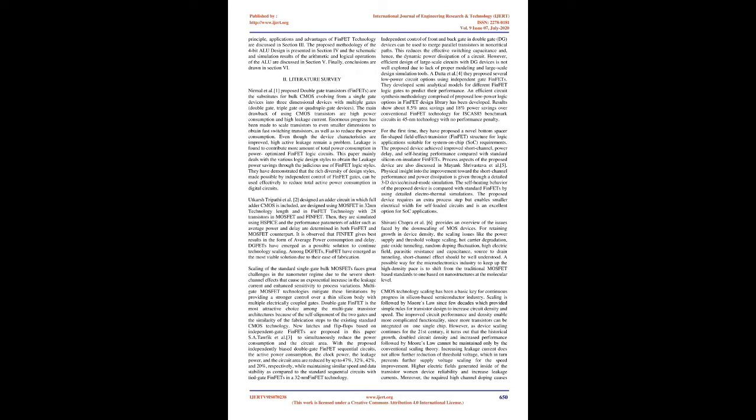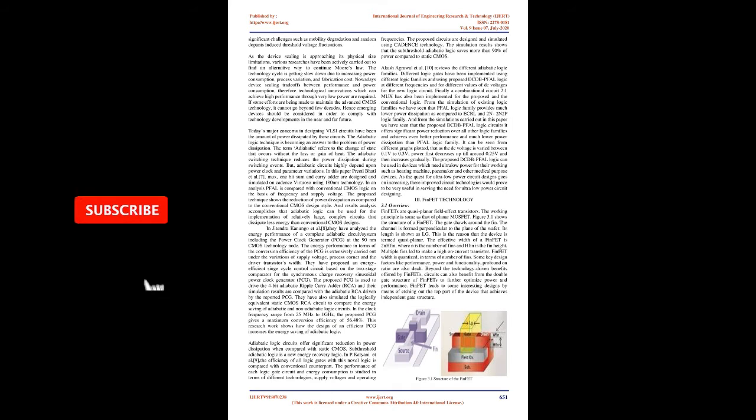DGFETs have emerged as a possible solution to continue technology scaling. Among DGFETs, FinFETs have emerged as the most viable solution due to their ease of fabrication. Scaling of the standard single-gate bulk MOSFETs faces great challenges in the nanometer regime due to the severe short channel effects that cause an exponential increase in the leakage current and enhanced sensitivity to process variations. Multi-gate MOSFET technologies mitigate these limitations by providing a stronger control over a thin silicon body with multiple electrically coupled gates. Double-gate FinFET is the most attractive choice among the multi-gate transistor architectures because of the self-alignment of the 2 gates and the similarity of the fabrication steps to the existing standard CMOS technology.